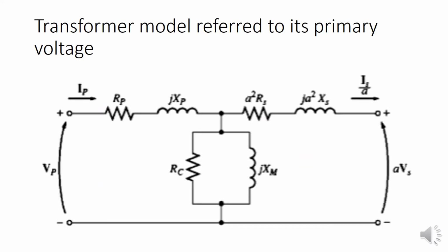This is another representation of the transformer, right? If we want to represent the primary voltage, primary resistance and reactance, and secondary resistance and reactance all together, we will use this model.